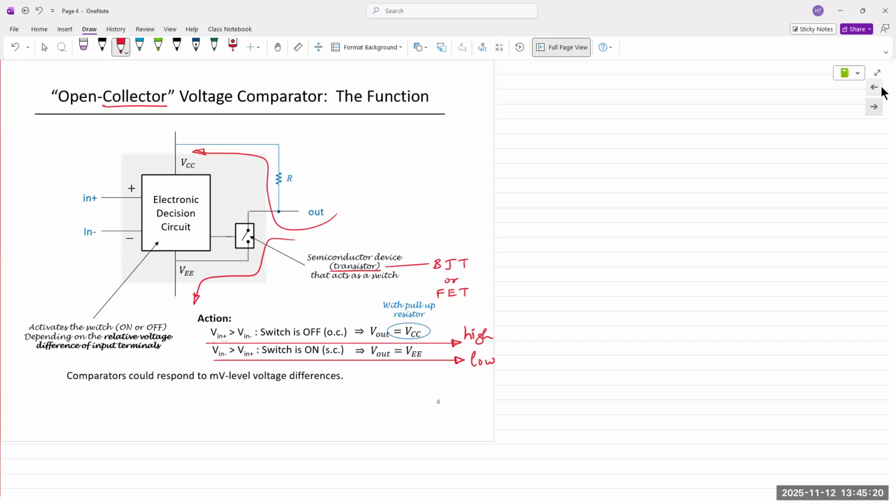With temperature sensitive applications, and there are even more specialized ones like scientific and engineering applications, where it could be even finer steps. So the thing here is that the finer the steps, the smaller the voltage difference between levels. Comparators are actually designed to sense even small changes in the voltage, going all the way down to the millivolt range.